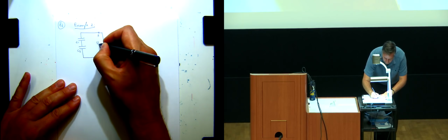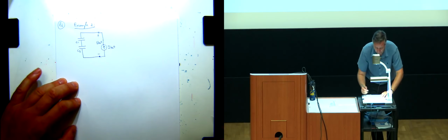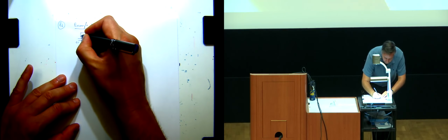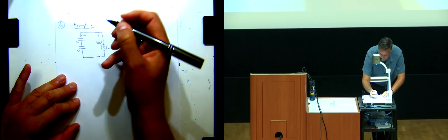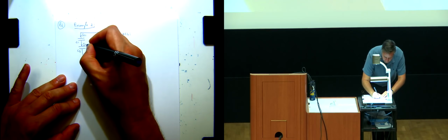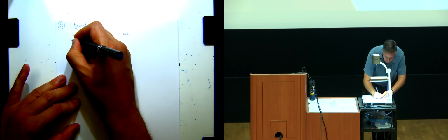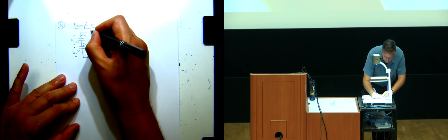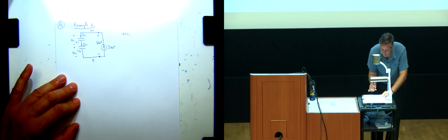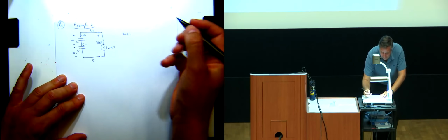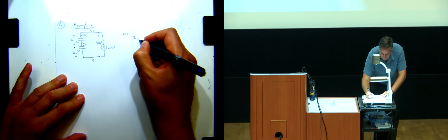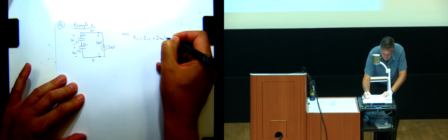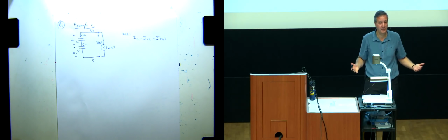And I'll look for the derivative of V test. So by KCL, I can label this: this is IC1, this is IC2, VC1, VC2, 0, U1, all that stuff. And so by KCL, hopefully this is easy. IC1 equals IC2 equals I test. Right? That's kind of the definition of things being in series.